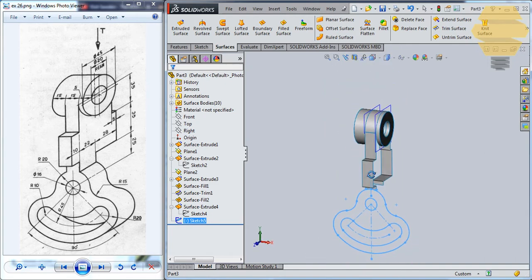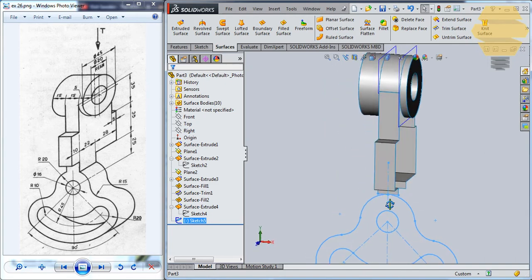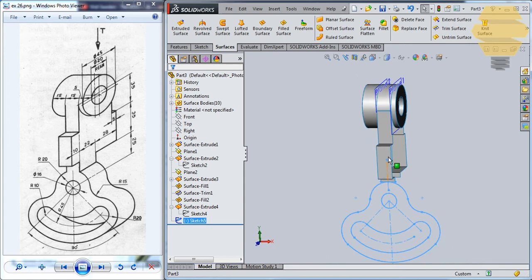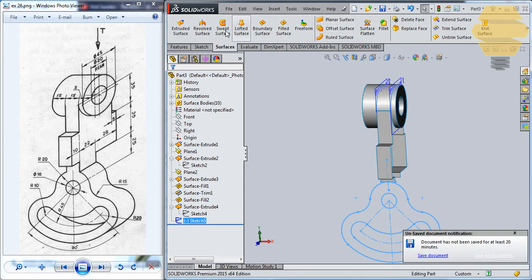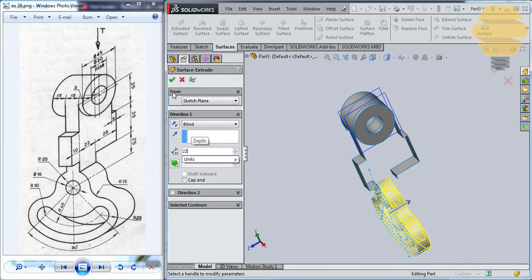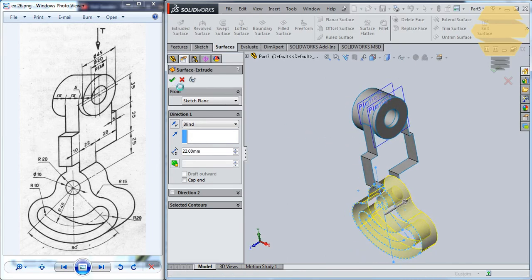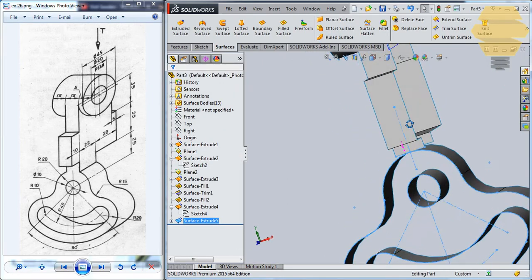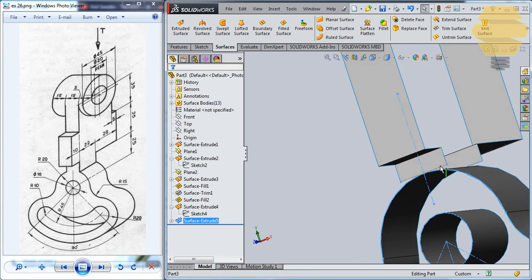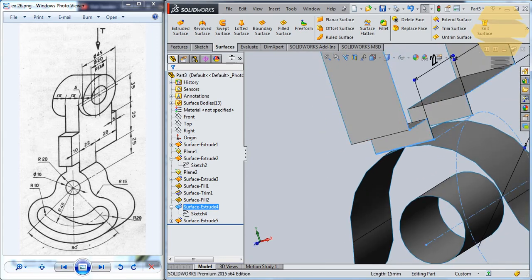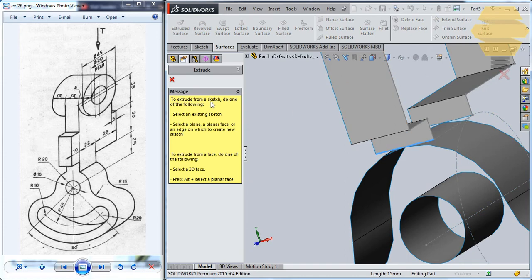So now, anyways, we'll just go ahead and do extrude. This distance could be 22, so that's 22 in that direction. Tick mark, tick mark. Alright, that's good. Now you can select this edge over here and go for extrude face.